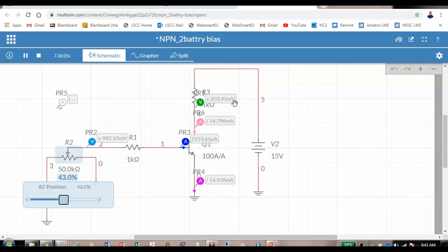Well, if we're looking at current gain, then the current gain is based on the collector current compared to the base current. So that means I would take 10.4 something milliamps, and I would divide it by 104 point something microamps, and we'll see this transistor has a gain of right around 100. I can just about do that in my head. So that means my collector current is going to be almost 100 times the base current. Can y'all see that? Anybody got questions?